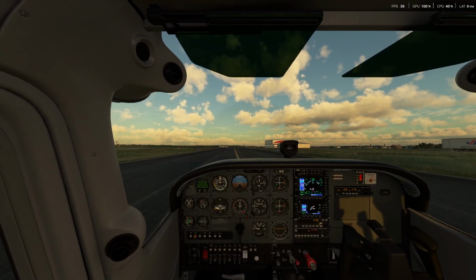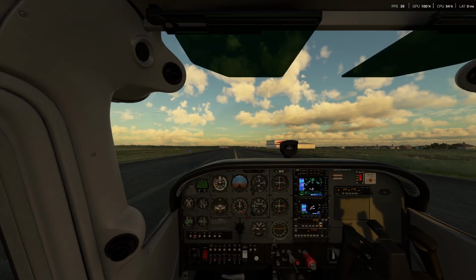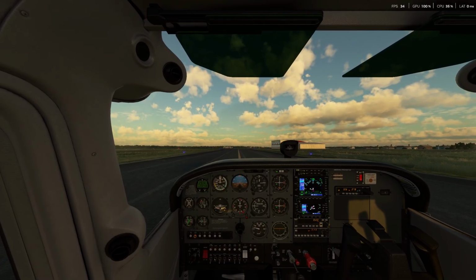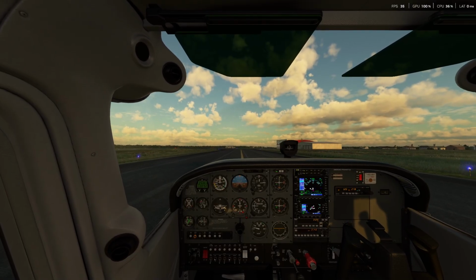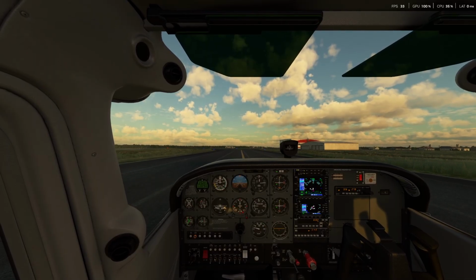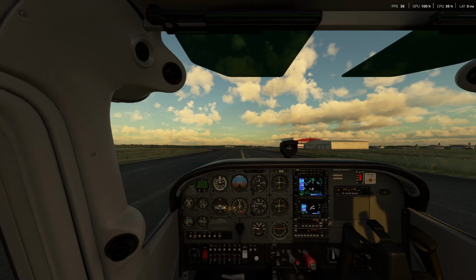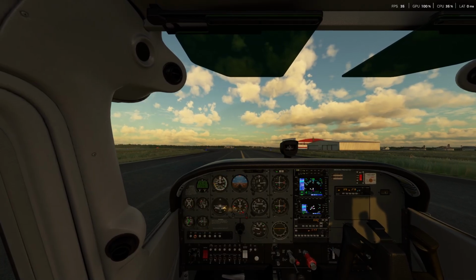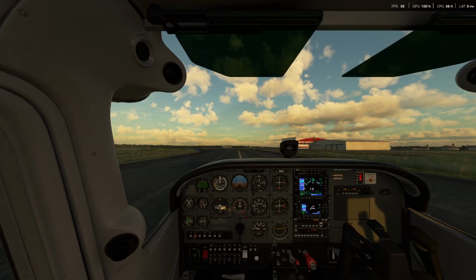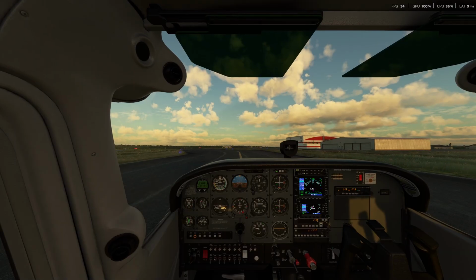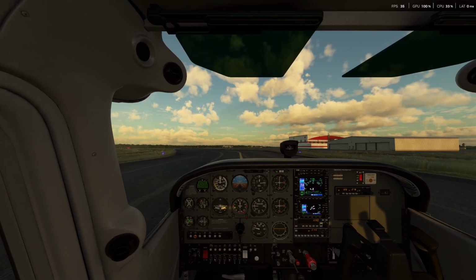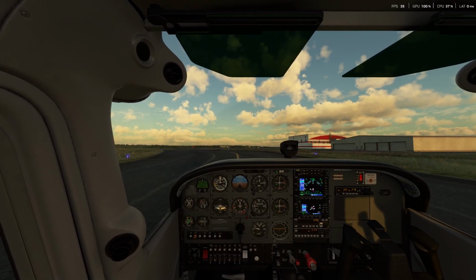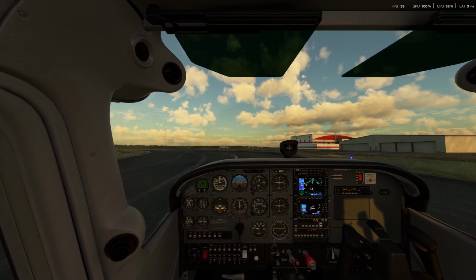So we'll pick up where we left off. If airborne without enough runway remaining, we'll make general control inputs as necessary to avoid any obstacles. We can make a right turn out to runway 24, runway 11. We also have the Trans-Canada to our north as well, if worst case. In the event of a non-critical emergency, I'll continue the takeoff to about 1,000 feet AGL, and I'll read and carry out the appropriate actions from the emergency procedures checklist.